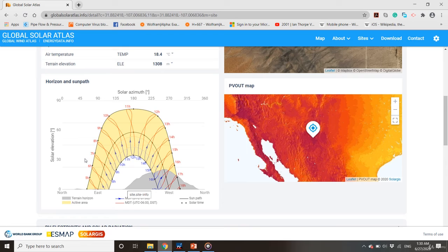If the load is maximum in the morning in summer, then you work here, get the average orientation angle from 8 a.m. to 9 a.m. and set the panel to it. If we see the average between 50 and 90 degrees, it's 70 degrees, so you set your panels at 70 degrees to get the most out of it. Same goes for the tilt or the elevation angle.